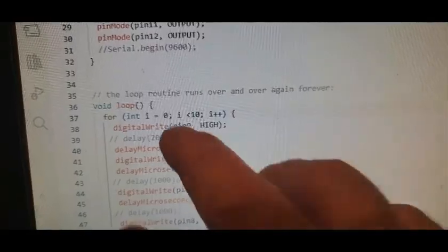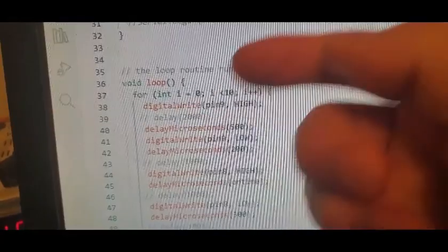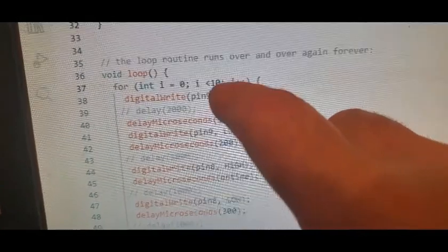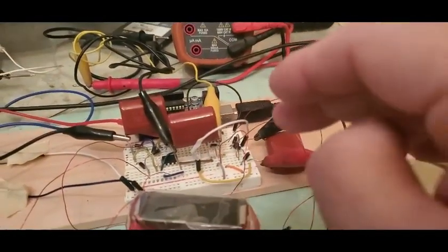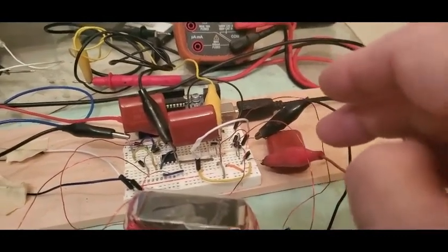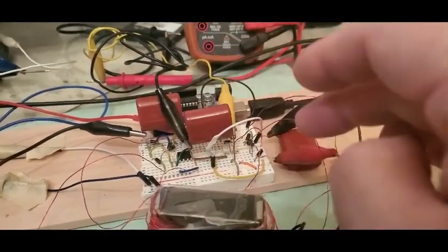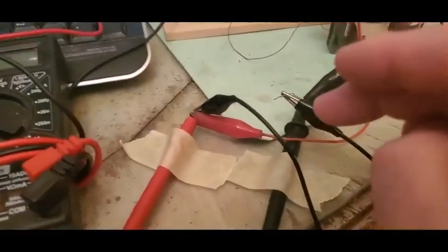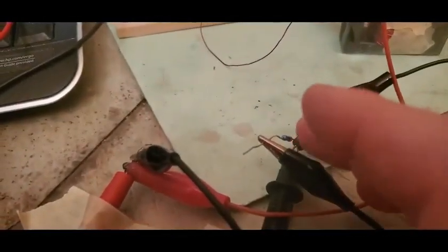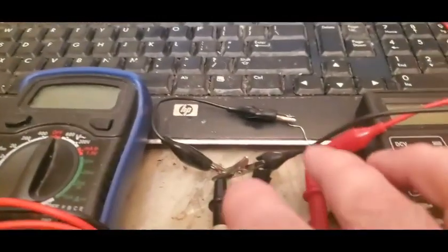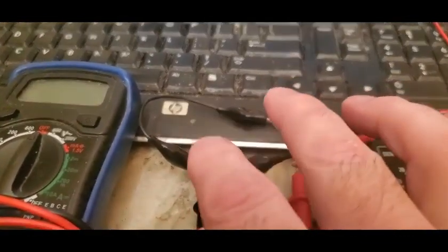Okay, so now let's run this 10 times and get rid of that delay where we were seeing it charge up to 10 volts, because otherwise that wouldn't be good. Before I mention the result, I have the secondaries hooked up, going into these other capacitors from a bridge rectifier, and I have them loaded. This is a 1K ohm resistor bridged across the 2 leads there, and a 1K ohm resistor on the other, bridged across the 2 leads there.